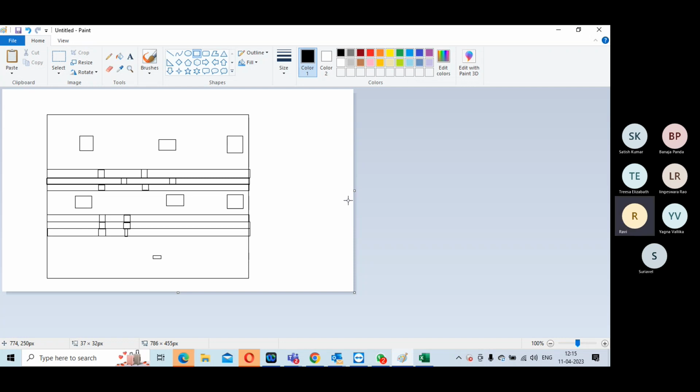You understand why we are not giving control of the macros to the automated flow, because the tool won't understand these things. We have to tell DFT that it is screwing up, go and divide this. Or it could be that this macro and that logic are required together because there is a control signal coming, like some enable controlling this and that overall.